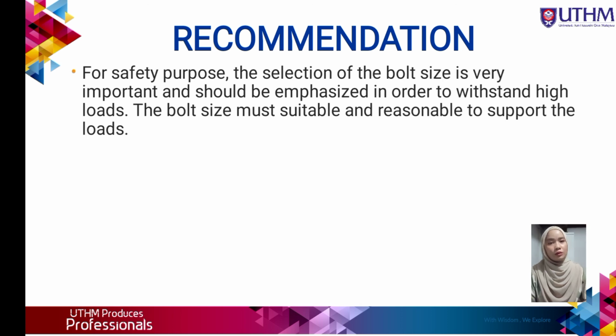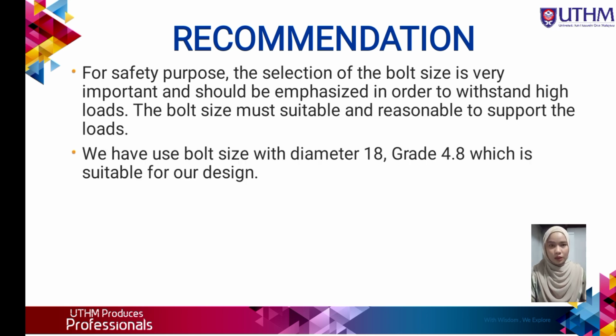The bolt size must be suitable and reasonable to support the loads. We have used a bolt size with diameter 18, grade 4.8, which is suitable for our design. As a result, this design has achieved the design requirements to ensure the safety of this stadium, because the resistance checking for every section is passed.